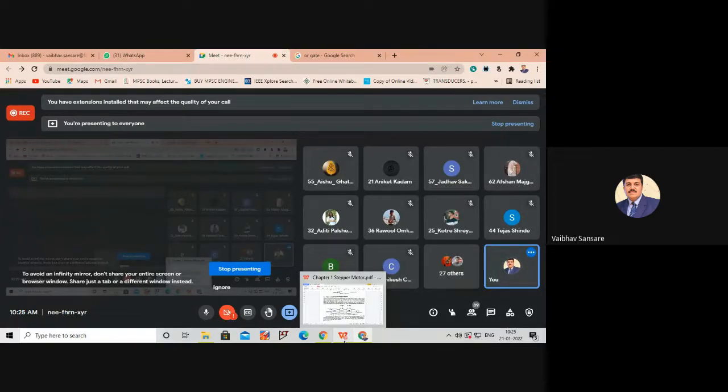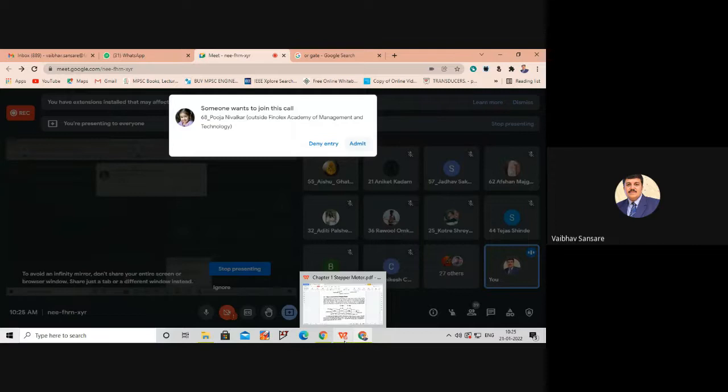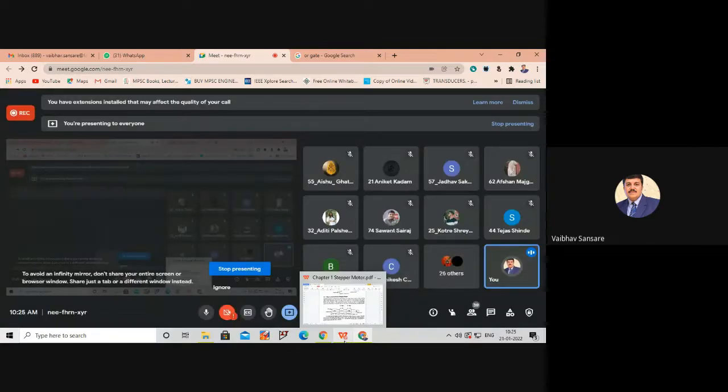That means whatever step angle the stepper motor rotates by, that rotation is not taken as feedback to the actuator circuits. So that is open loop control. The excitation control of the stator phases does not depend upon the actual step angle by which the stepper motor rotates. So there is no feedback loop in open loop control of a stepper motor.